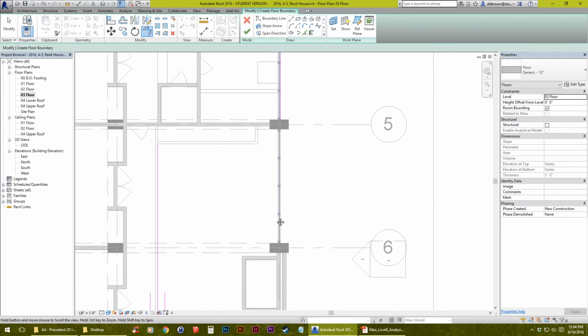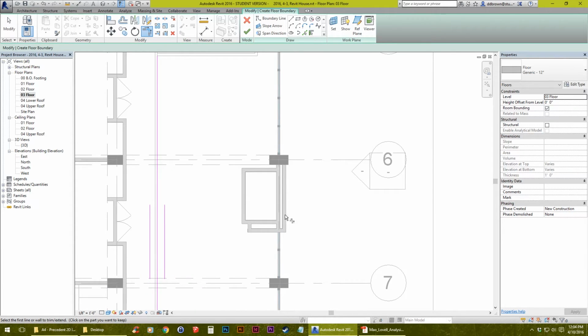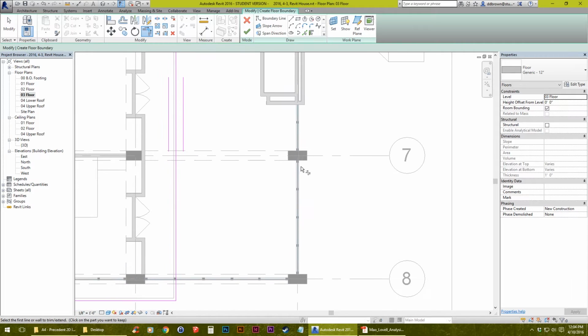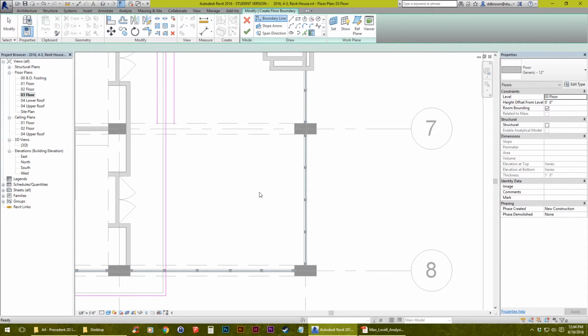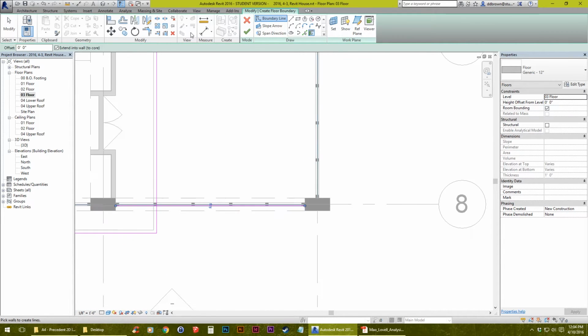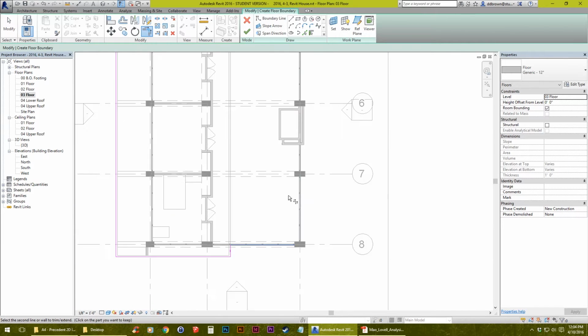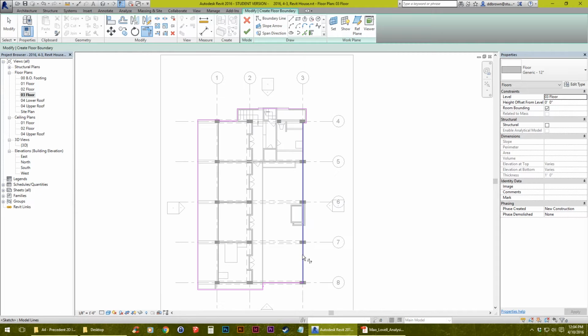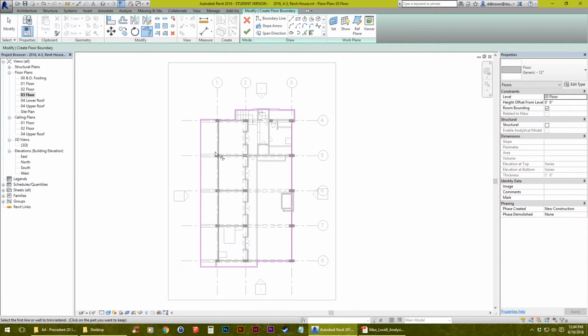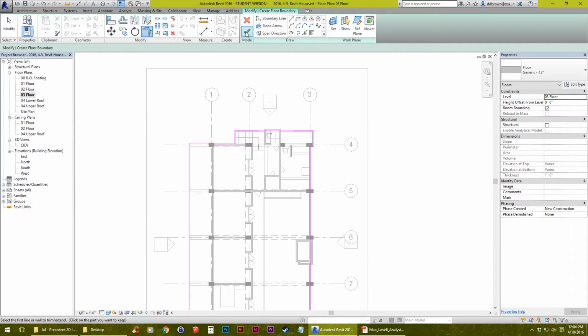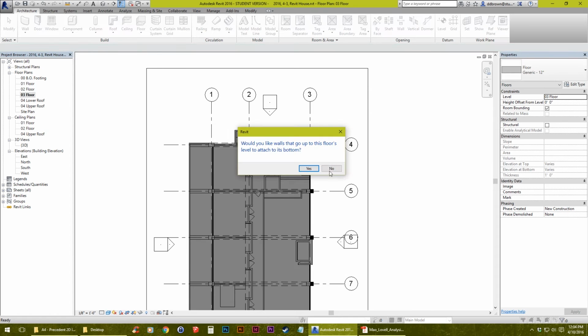And that line will basically continue straight across. I'm just going to ignore this little section here. I'll use the Pick Walls tool, pick this curtain wall, and then I'm going to trim these two lines and extend to the corner these two lines. Okay, so that should be a continuous loop. We're going to click OK and the check mark. Just no for now.